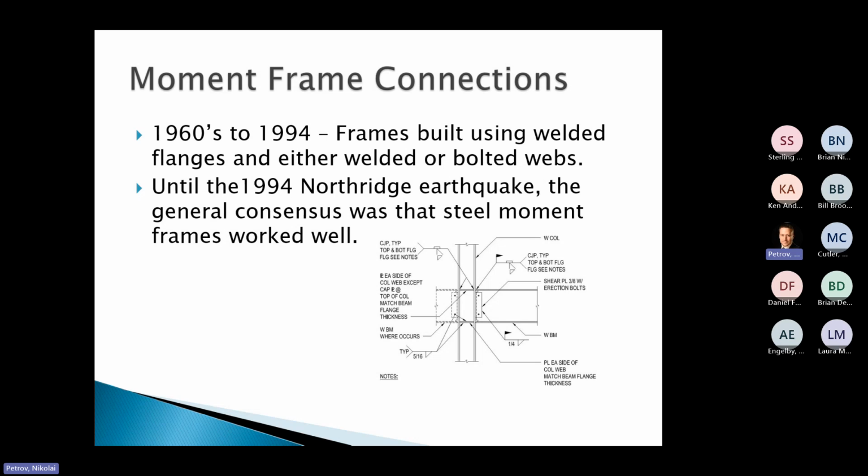When that happened, moment frames really took a hit. That's why we still feel today that we're a little cautious in recommending moment frames for a project to an architect or especially a contractor. They're like, oh, we don't want moment frames, they're too expensive. That's the general consensus: don't do moment frames, they're too expensive, it's too costly in the field. The reason that sentiment exists is because of this earthquake and what was learned in the 1994 Northridge earthquake.